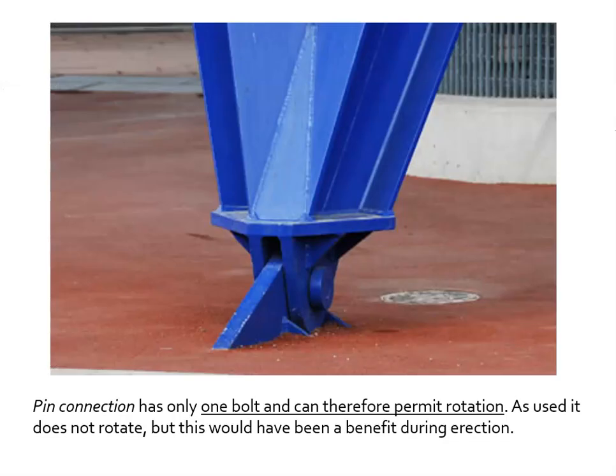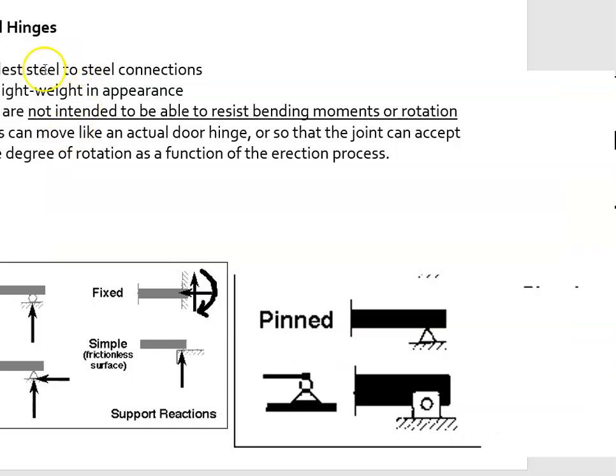All right, so let's look at one of these. So there, that's a nice looking pin joint right there. It has only one bolt and therefore would permit rotation. So it's not rotating now, but it was probably allowed to rotate when it was put up, actually. And it would have been a benefit at that point, to provide some flexibility. So let's just jump back one more time. Simple steel to steel connection, very light in its appearance.